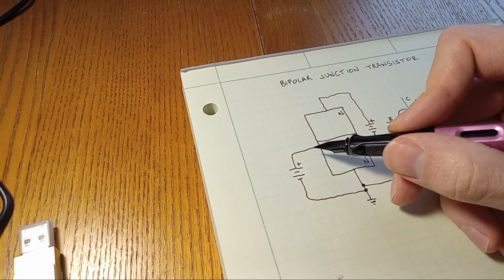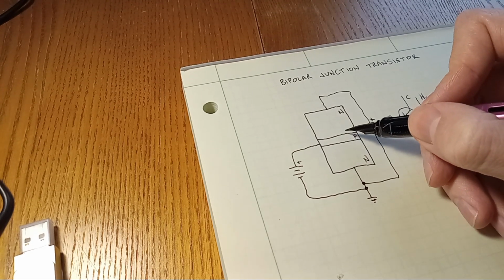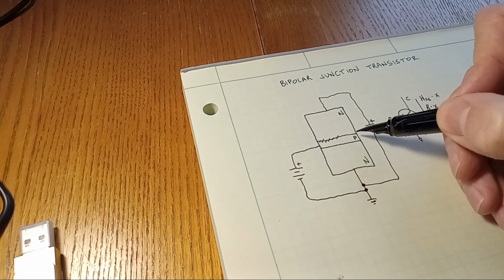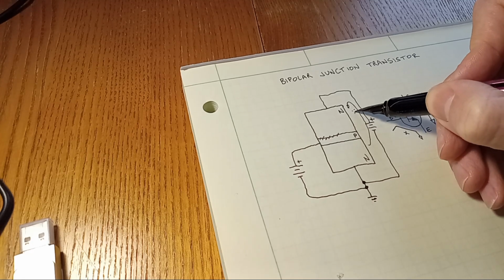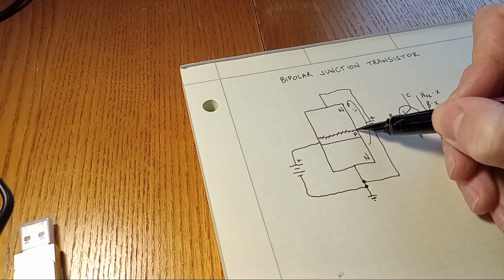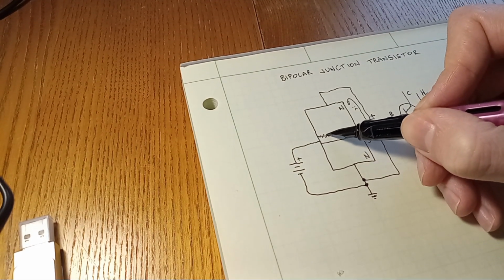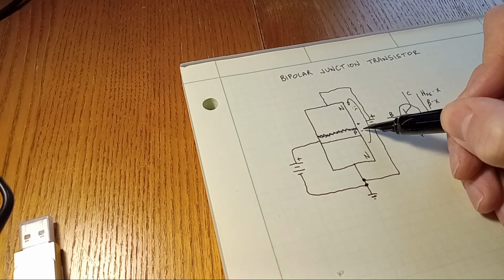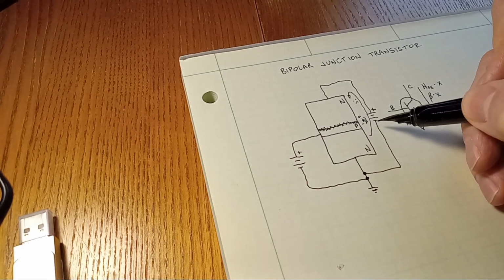So without this voltage being applied, there is a reverse biased PN junction here that does not conduct. So current cannot flow through the transistor as a whole. It's very sad because this depletion region here prevents conduction. However, there is still an electric field present across the depletion region. This is important to note, dear viewer. I'm sure you are at the edge of your seats.